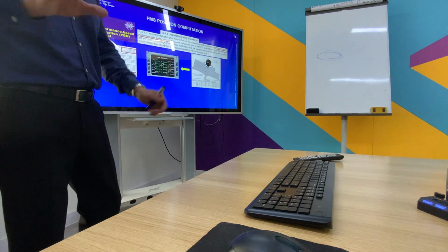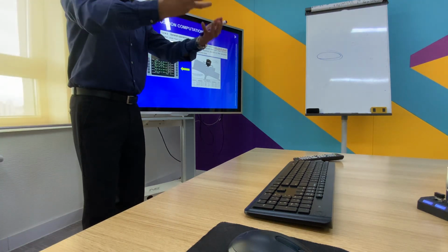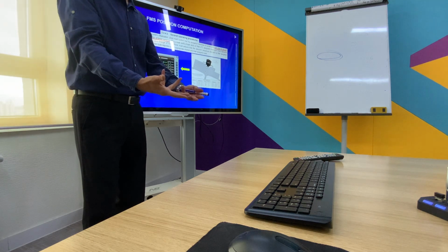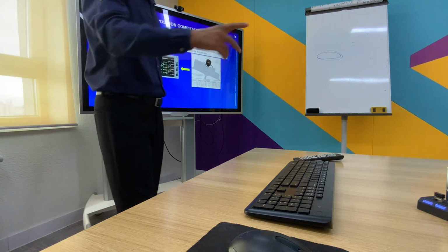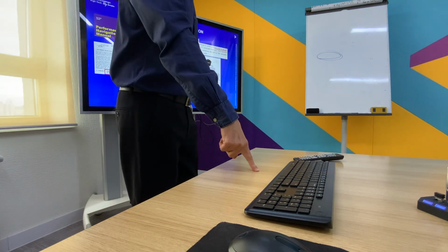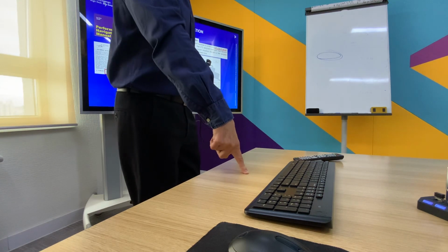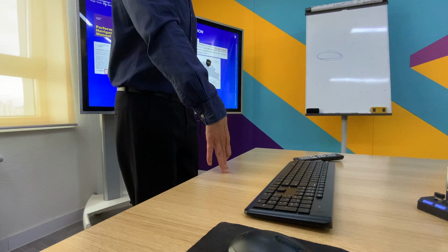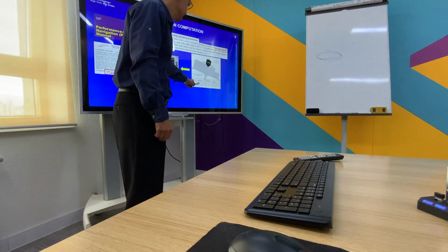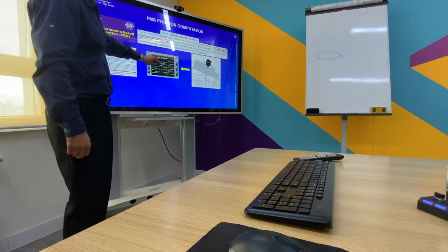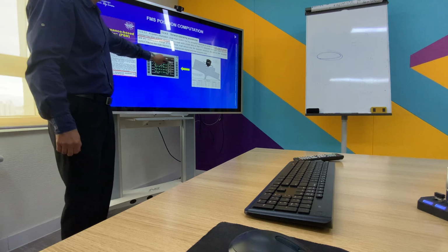What I suggest, before loading the flight plan, is to check the navigation database and verify that it's valid. Remember the date. After that, go to the position sensors and check the position against the position that the FMS is retrieving.